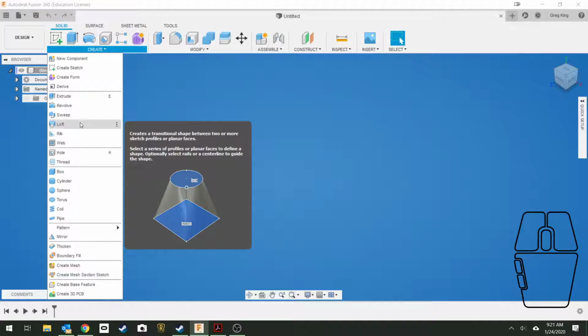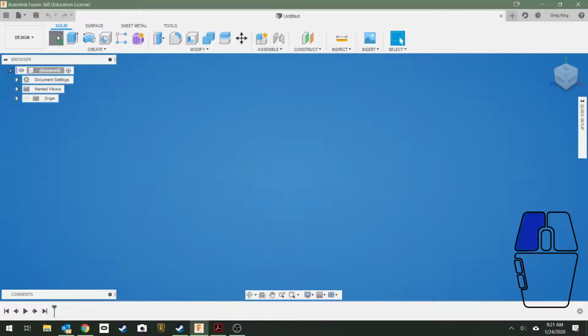If you look at number 1, we're going to make the shape that is on top, the T, and then the shape that's in the bottom, which is a bigger, thicker T shape, and we're going to make the whole thing in one move. Those of you who actually were able to make this shape, you probably did it in at least 2, if not 16 moves for some of you. So we're going to do this in just one move by doing a loft from the one to the other. Let's go ahead and take a look at what it takes to make a loft first, then we'll go ahead and make this shape. So make a sketch,